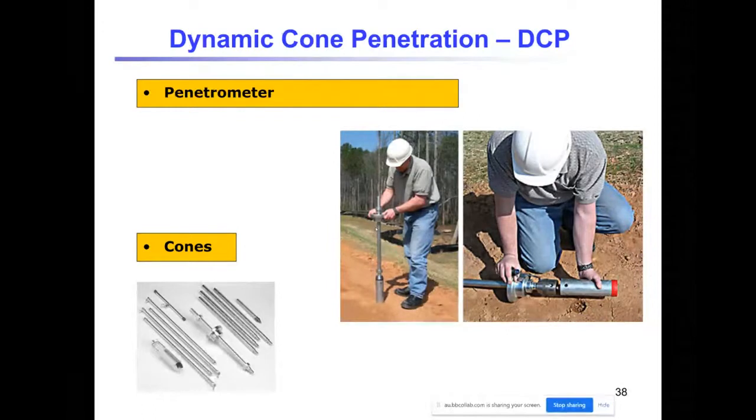We are applying the drop of a hammer. So you can put this shaft upright, then lift the hammer and drop it. And when you do this, after 5 blows, you need to count the level of the penetration.